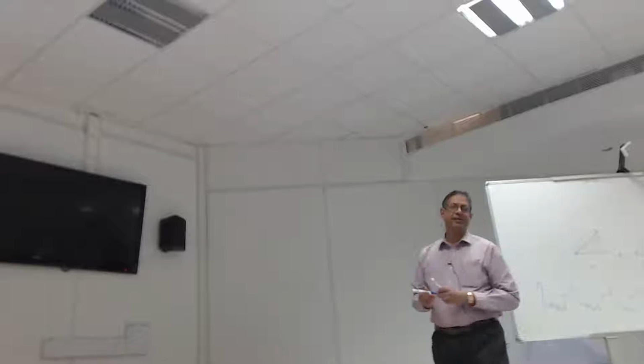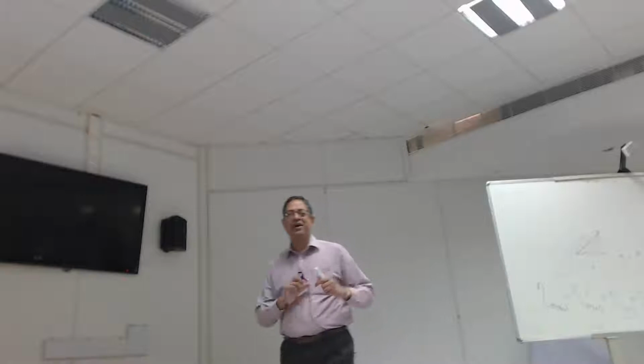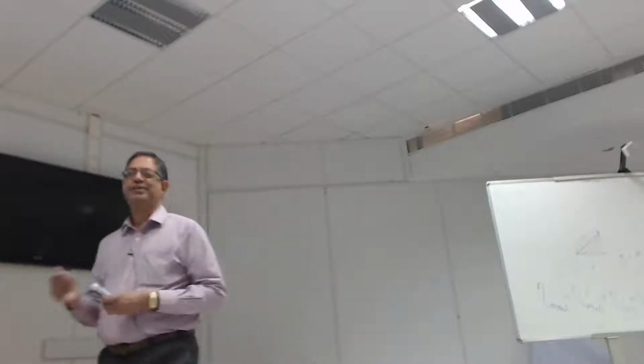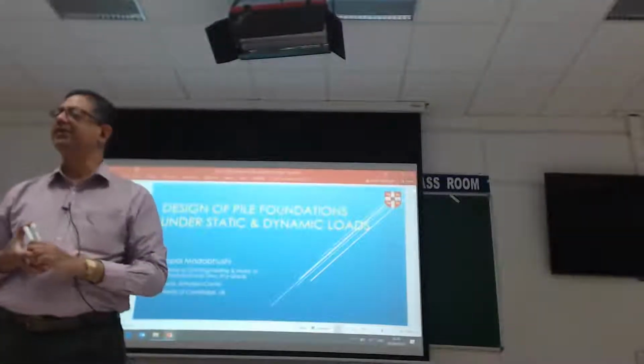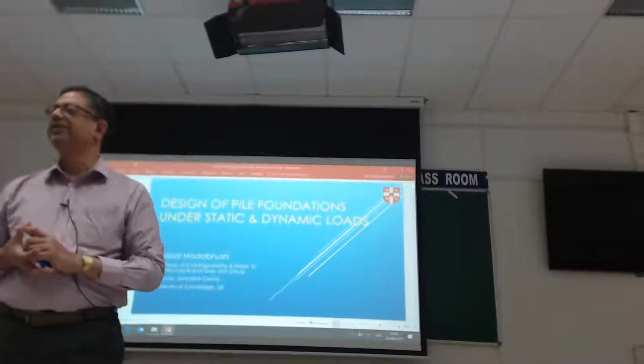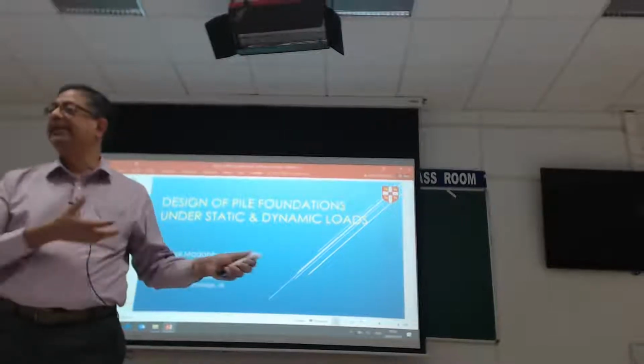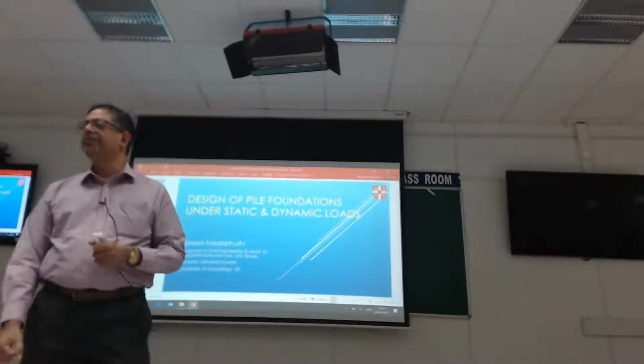And what you can show is these 2 components are quite small compared to our material damping. So those get drowned out by the big number. If I add small numbers to a big number, the big number always dominates, right? So it turns out that the viscous damping therefore does not play a big role in these types of large strain problems.